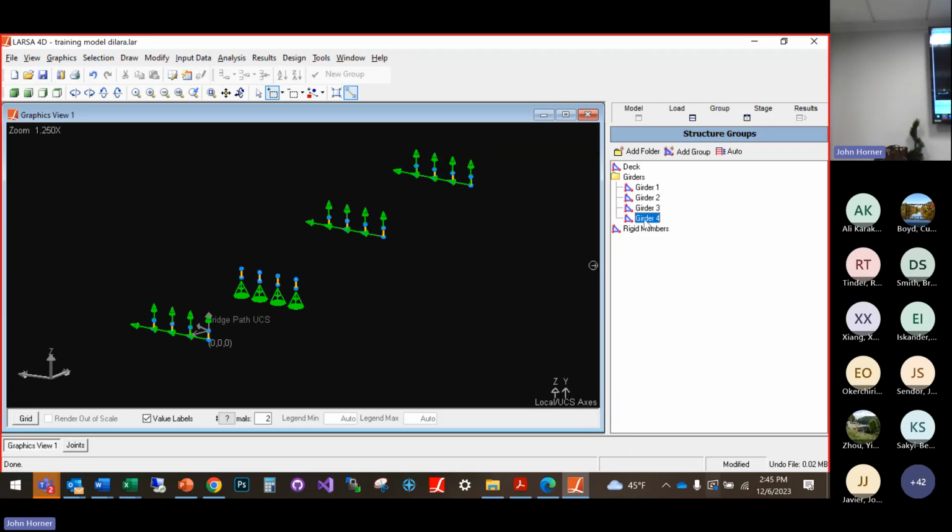We have a question. Okay. Did you select widgets? No. This is local selection. Select spatial, then say geometry, members, and select rigid members. Members with property, just click material, and value should be rigid members. Here we are trying to select them. You just click select, yeah. This one will select rigid.